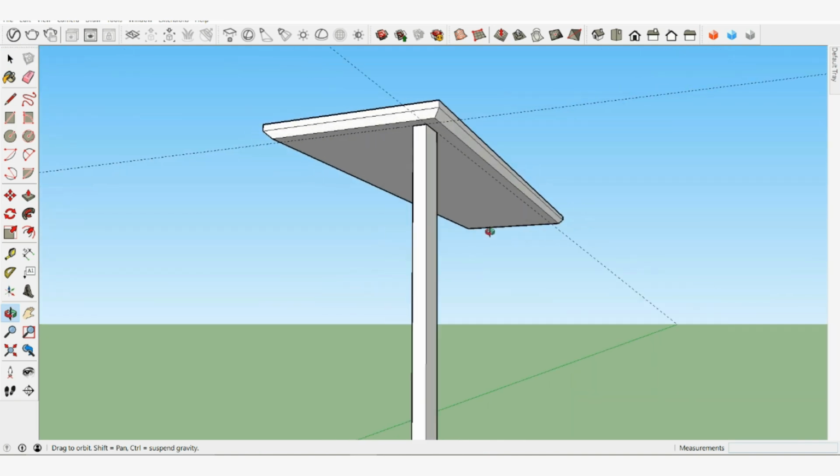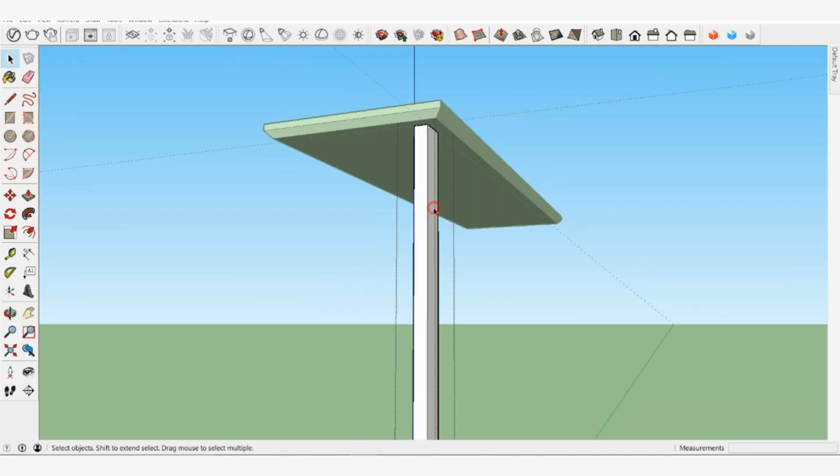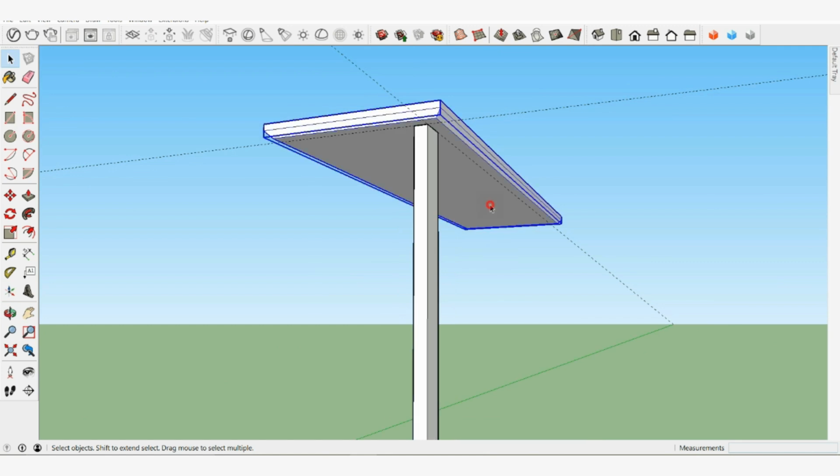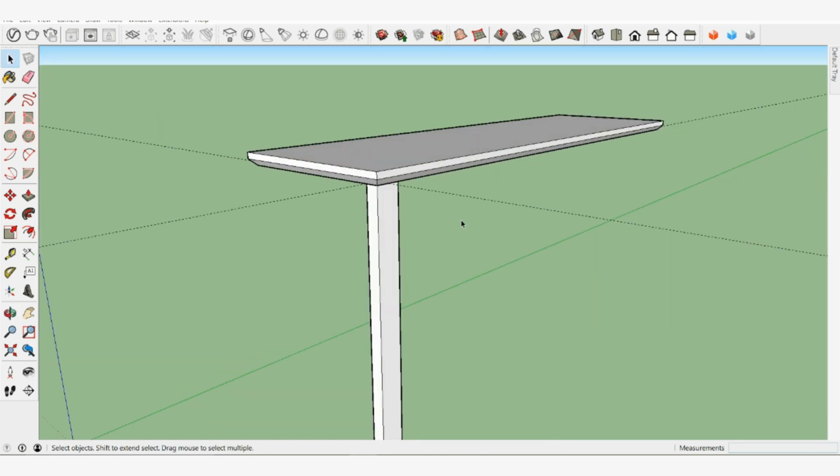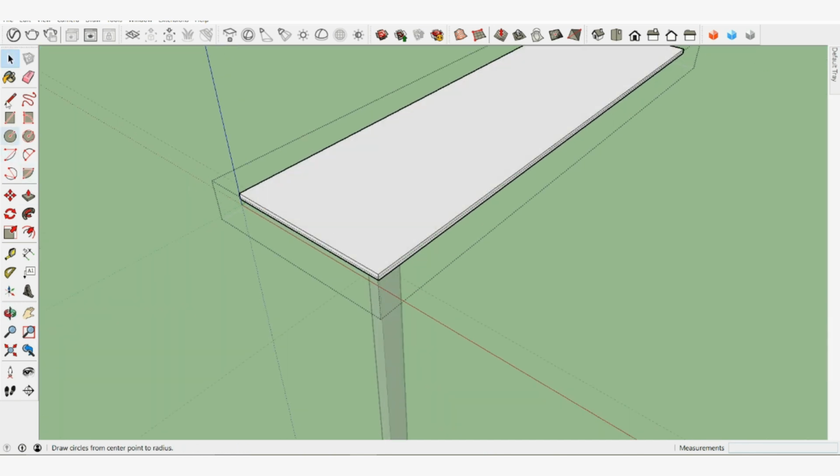Use the select tool and double click on the tabletop. The bounding box changes, indicating we are now editing the group. Still with the select tool, click outside of the dotted surrounding box to close the group. Practice this a few times with our group and component. Double click on one to edit it, click outside to close it, and do this several times.